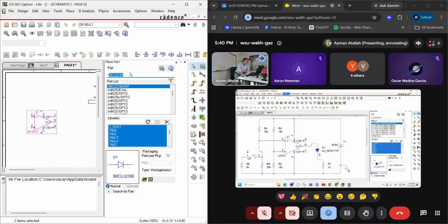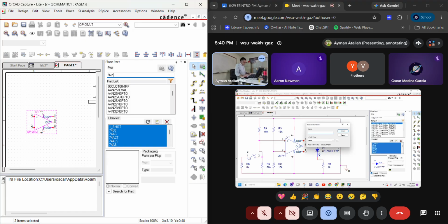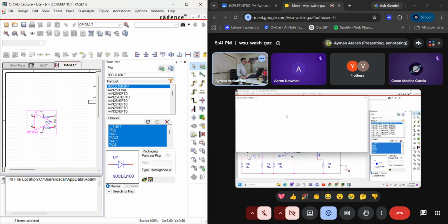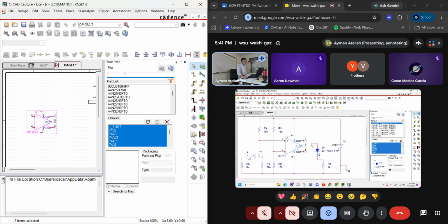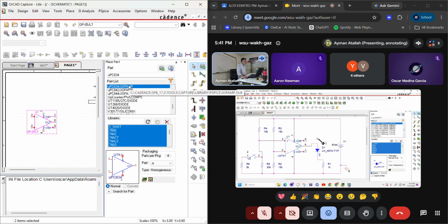Okay. So the simulation will be PSpice, new simulation profile. I'm going to use transient simulation. For how long? For 4 seconds, and this is 1M. Simulation, transient time, 4 seconds, 1M. Apply, okay. So I need to measure the voltage here, or you can measure the current, no problem. You can put a probe to measure the current. Okay, I can measure the current here.